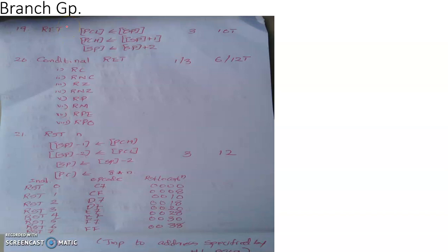This will be the instruction given at the end of a subprogram that is being called using the call instruction. After execution of the subprogram, the control must be transferred to the main program. To cope with this act of returning back to the main program from a subprogram that is being called using the call instruction, this instruction return will be used.